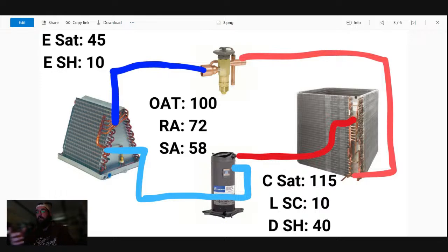Could be oversized, as in the system. Yes, well, I say yes. It could be, yeah, but there's something more specific that is affecting this, and you can tell by the temperature readings. So, discomfort from humidity. Well, that's where we have to come in. They don't know how to articulate that most of the time. So is it from humidity? Well, we have to determine that.